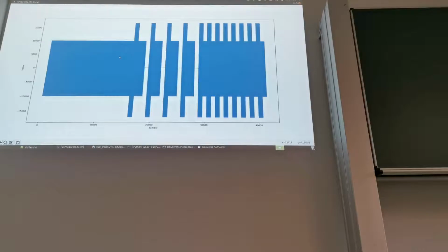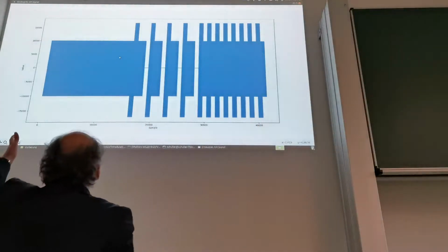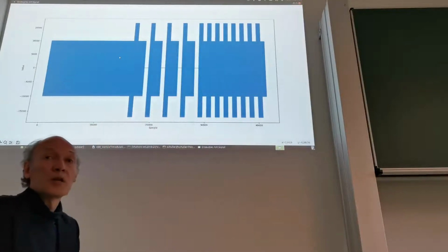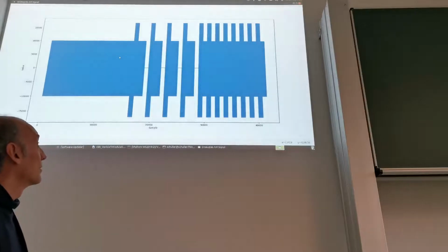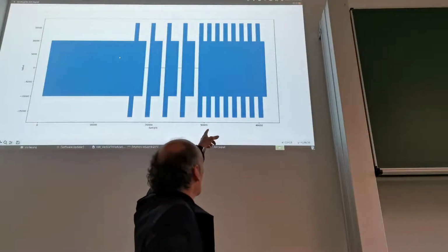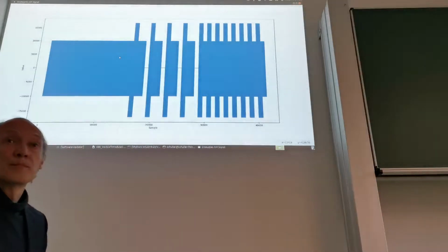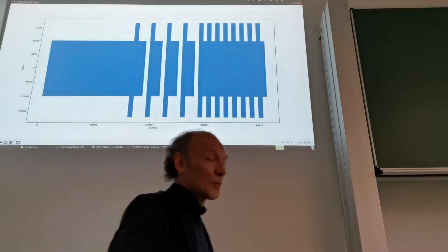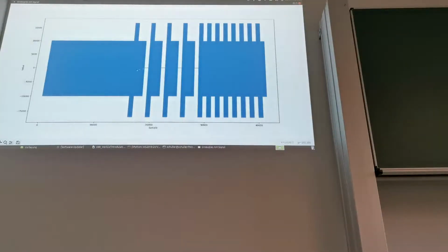And you can see here in the beginning, we just have a carrier. And then we can see here those changing amplitudes. They come from the 1 and 0 bits. And you can see here those short bursts are the clock. Right? And here you can see those bursts appear smaller at this point because there's a 0 bit. So here there's a 1 bit, and here there's another burst, but it appears smaller because there's a 0 bit. Right? Same here. So this is the original clock rate, and it continues here. It's just that we don't see it in this plot anymore.